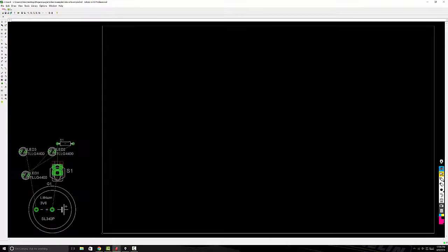Your new window pops up. Maximize your window, and you have your physical board design now. One thing that I noticed that's missing on mine is the grid. So you can hit View Grid. I want to turn the display on. My manufacturer works in centimeters, which is metric, so I want my grid to be in millimeters, which is also metric. So switch those both over. The style will be lines instead of dots. And I can hit OK.